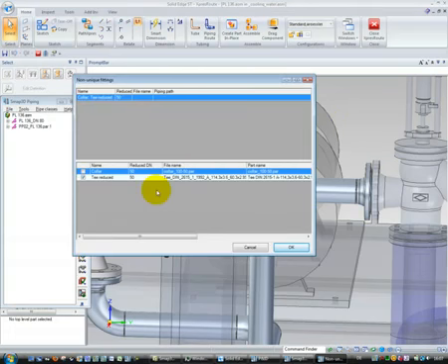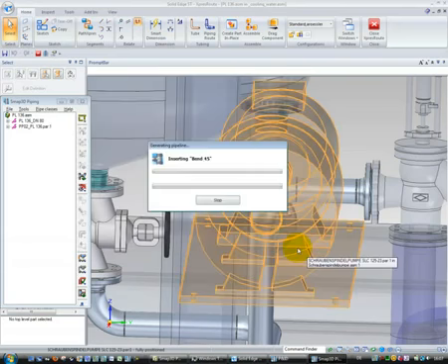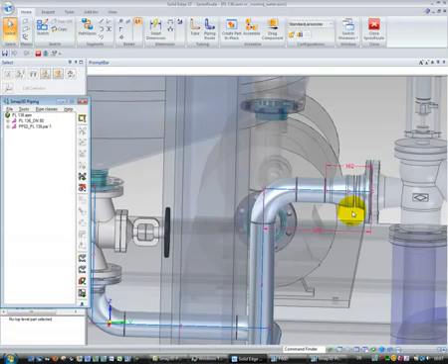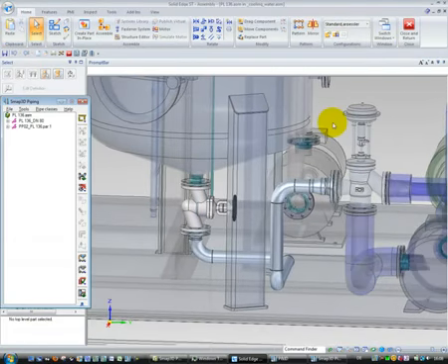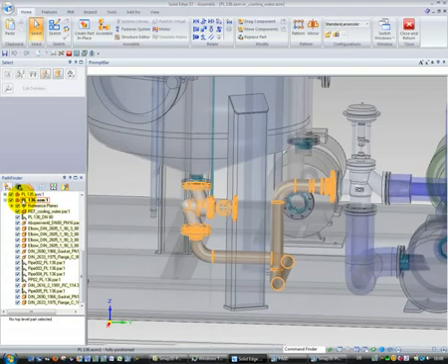If for the new diameter there are different parts defined for the same position or the same standard situation, then a non-unique fitting dialog appears and the user has to select the required component or the standard that is defined, and then the process works further. At the end of the process we also get the corrected situation for this expanded pipeline. Then we can leave the ExpressRoute environment, and in our Pathfinder we see our pipeline assembly where all components which must belong to this pipeline are included.